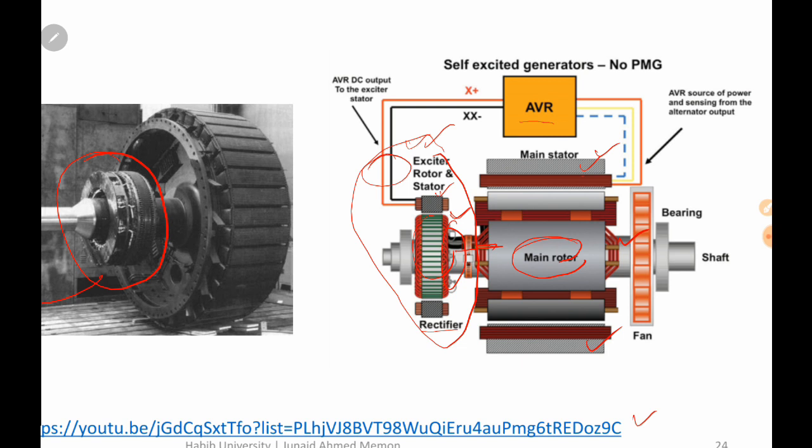This is an important device installed in generators as well. You can see one application of control, which is to control magnitudes of a higher quantity by controlling the magnitudes of a lower quantity, the field winding, which we are controlling here. And you are controlling a much larger current supplied from the main stator.